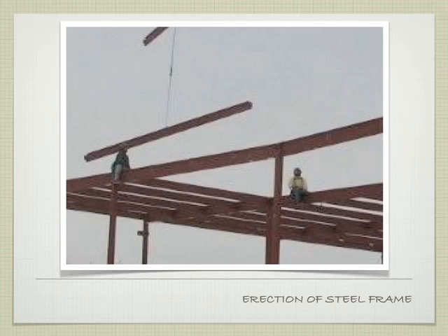It depends on the speed of the building, how quickly you're building these together. Generally, it's non-permanent because the erection of the building is much, much quicker than the process of being able to pour a concrete deck. So if you're going to use a composite deck, which we'll talk about in just a second, which has steel and then a concrete topping layer on it, you've got to wait for the concrete to cure before you can really walk on it.